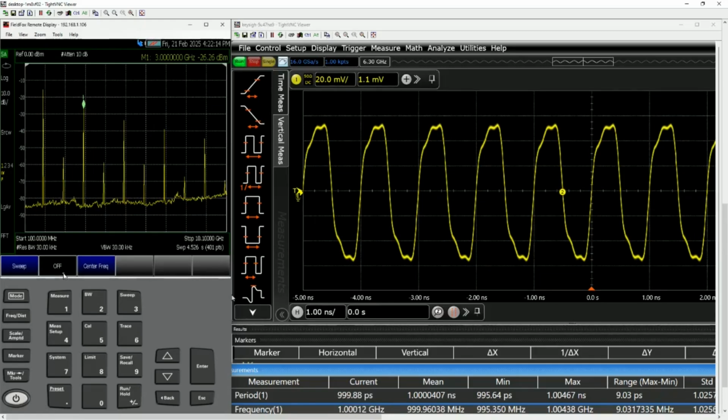But right now we want to use port 1 to transmit a different type of frequency, so we select off. This is where you set the center frequency, this is the power, and this is the on-off button. Let's look at the physical setup.